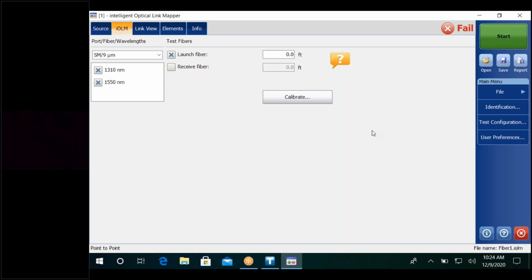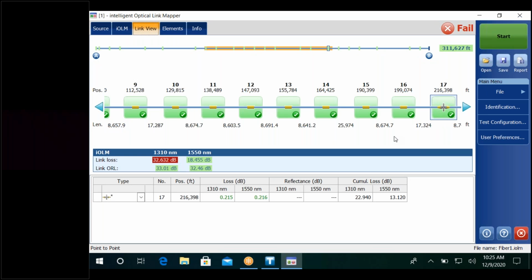They really want to see that you've done it. I can tell you that a lot of service providers, Verizon, Google, AT&T, CenturyLink, Lumen, Qwest, whoever they are, they're now accepting the graphical interface, this GUI. Now, maybe you want to see the OTDR trace. You're able to go in your settings and say, listen, I really need to see that graph. I trust this, I know it's working, but I'm just used to seeing my results in a graphical view. You're able to have that result.